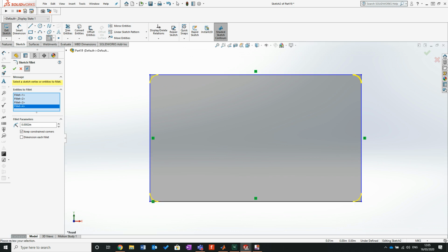Now, what I'm doing is putting these fillets on. If you remember earlier, I was talking to you about on the drawings, it doesn't actually say, but them fillets are there. So what we can do is control them fillets. And then if we were going to the boss, we could literally say, I don't know what sizes these fillets are. There's no real spec for them, but I've placed them on just in case you do decide to start adding a particular reference for them. So then I'll click OK on that.